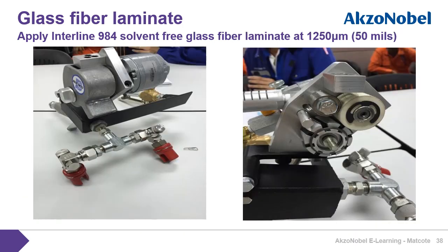Now moving on to the specialised spray gun itself, on the left you'll see the twin spray tips which allow the glass fibre roving to be wet out completely by the resin, and on the right the safety cover has been removed and you can see the razor blades and the rubber ring which ensure the glass fibre roving is chopped.